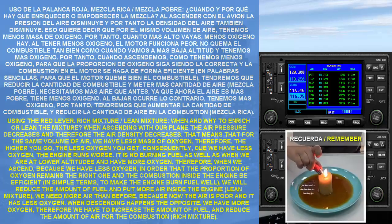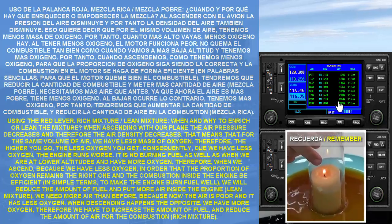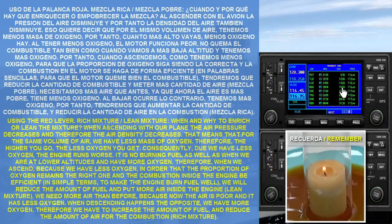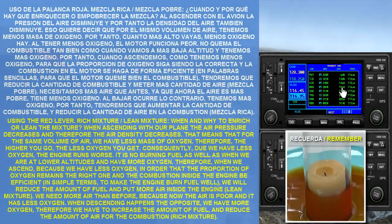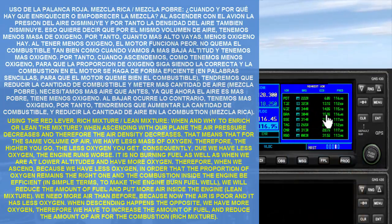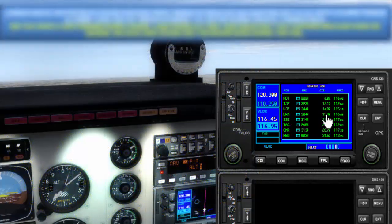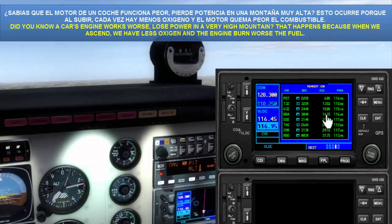Okay, for that reason we need to use the red lever to enrich the mixture or to lean the mixture. And what happened is when we are ascending, due to the air pressure decrease and therefore the air density decrease, that means that we have less oxygen in the air, and consequently, if we have less oxygen in the air, we need to put more air inside the engine to make the fuel burn better. Okay, that is very important.